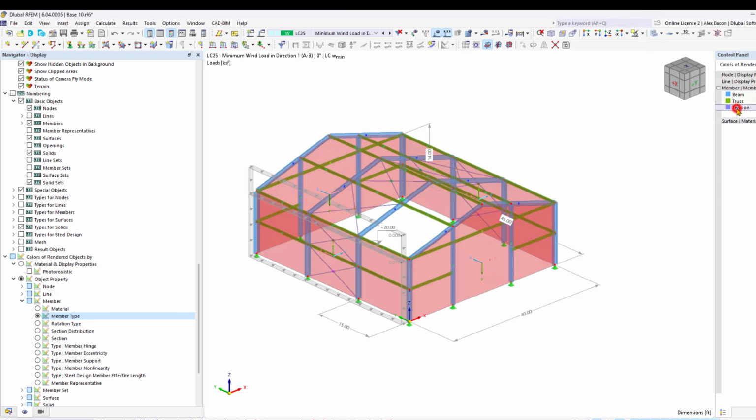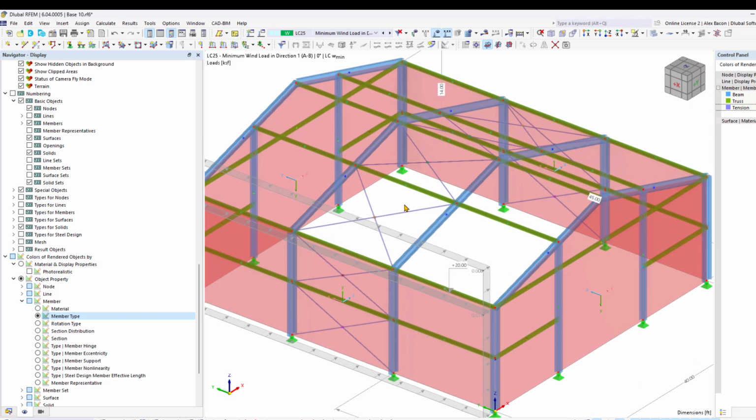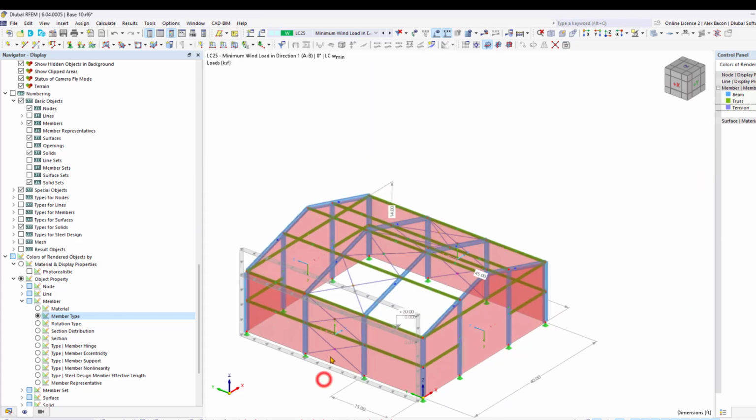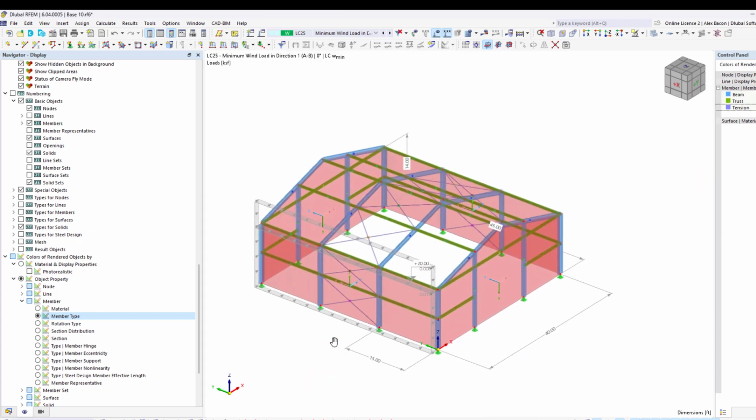In the color panel on the right, you can see tension members are purple, and you can see that our cross bracing is set to tension only. These members will fail automatically when absorbing compressive forces. To avoid this instability, you can activate the Exceptional Handling option in the Reactivation tab of the Static Analysis settings.